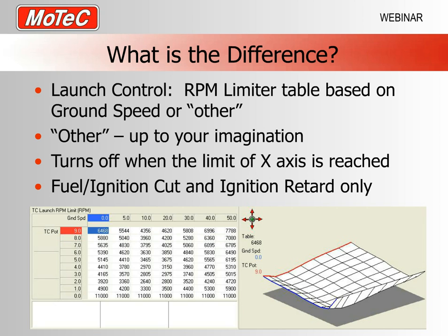Another thing I have here on the y-axis is a traction control trim pot. This particular customer has the ability, with a 9-position switch on the steering wheel, to change it. So if he goes out on the track and suddenly it starts to rain, he can adjust his launch control to suit something that he would have tested before for wet conditions, dry conditions, hot, cold, different tyres, those kinds of things. And just to be a bit smart, down the bottom you can see we've got a more or less off situation, that's what we would call the burnout mode, or if he wants to go out and do donuts because he's won the race, he can simply change into a mode that will allow him to do that as well.